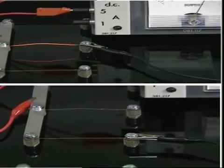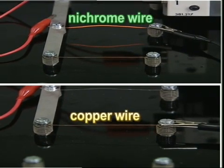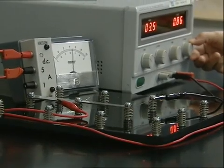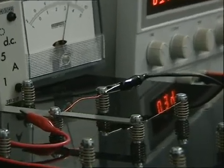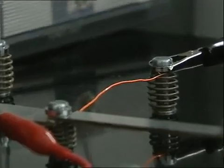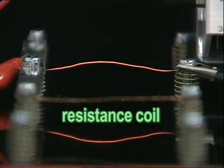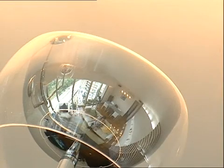A moment later, the copper wire does not release light and heat. But it is obvious that the nichrome wire releases light and heat. From the above experiment, we can infer that if the same electric current flows through two pieces of metal wire, the heating effect is stronger for the wire with a higher resistance. The metal wire with a high resistance is known as a resistance coil or a heating coil because it can heat up. The heating effect of an electric current is the basis on which many electrical appliances generate heat and light.